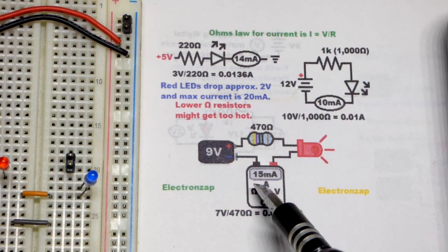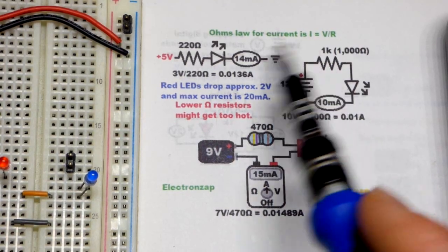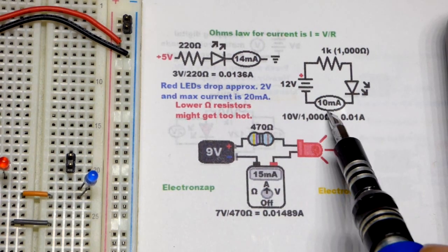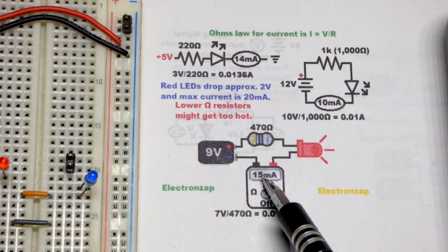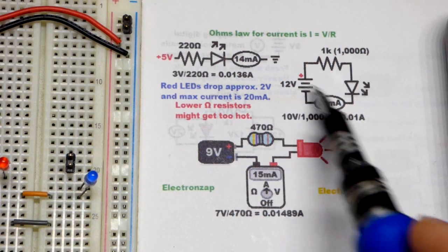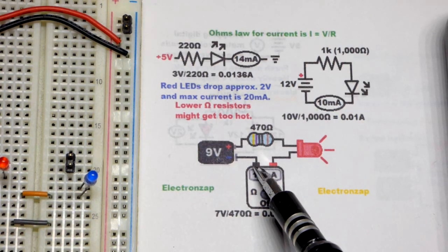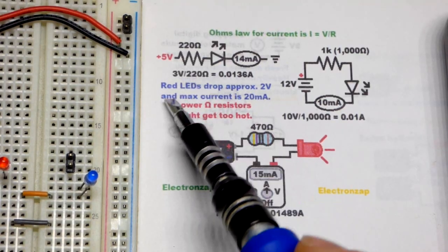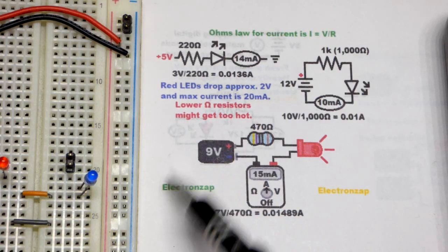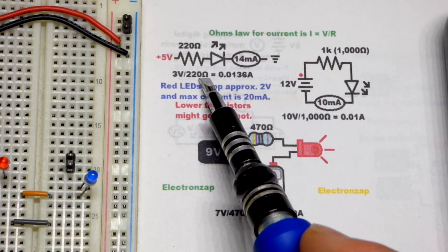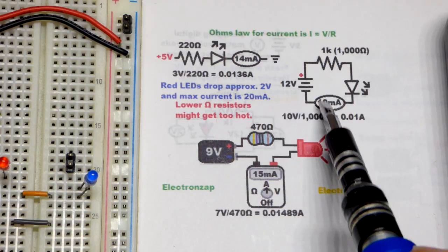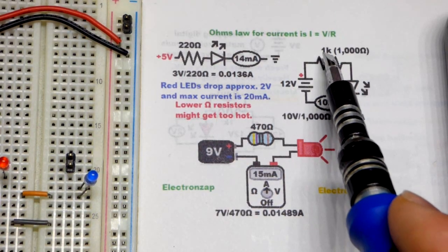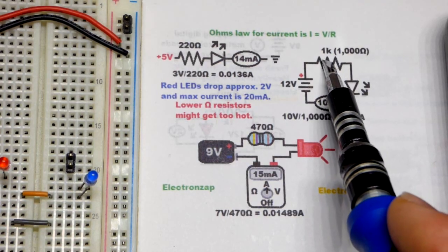So in any case, we have the pictorial drawing, the schematic drawing, and so on. That's how you will look at them. I added extra info. I put the current that you can expect right there. Approximations are perfectly fine. It doesn't have to be spot on. And I did the math here. Most schematics will not do that for you. That's something you have to do. And then, again, when it comes to 220 ohm resistors and 1000 ohm resistors, especially the 1000 ohm resistor, for each volt across it, you're going to get 1 milliamp of current.